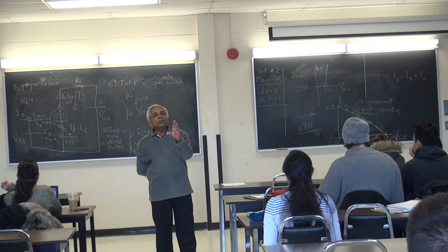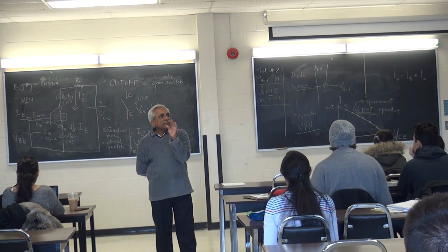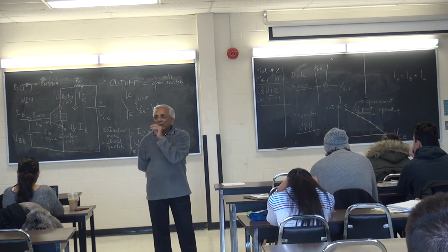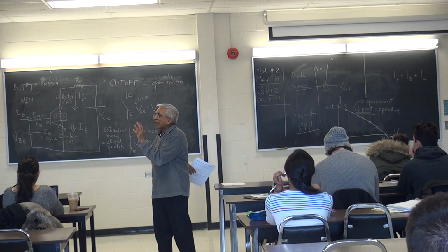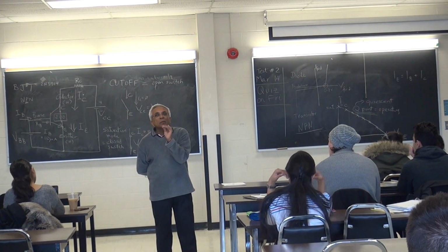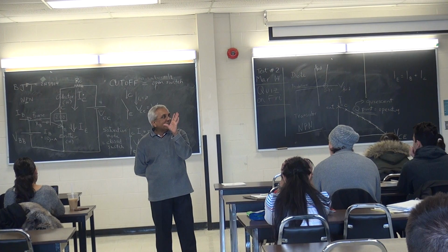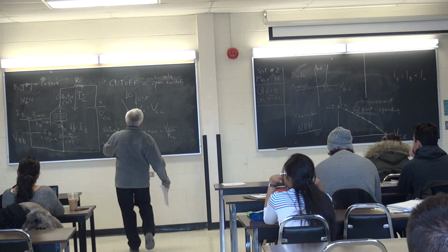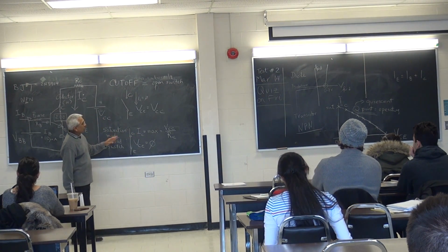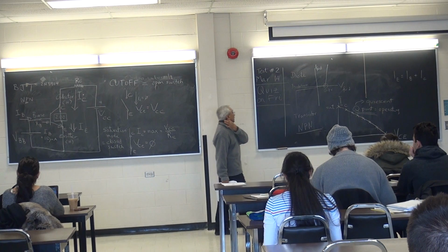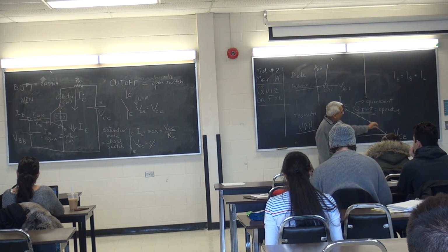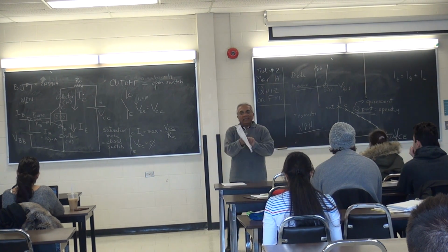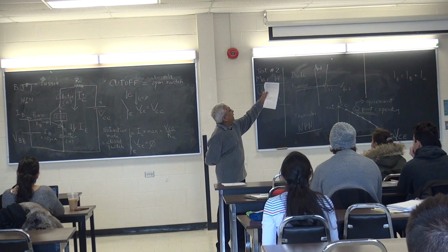When a transistor is used as an electronic switch, such as with our digital circuits, when we are talking about an AND gate, OR gate, NOT gate, all those chips, we have the transistor acting either on or off, open or closed. That is when it's either in the cutoff mode or in the saturation mode. When it is in an amplifier mode, then it is going to be somewhere between cutoff and saturation. Okay? So, that's my graph at the top of page 9.